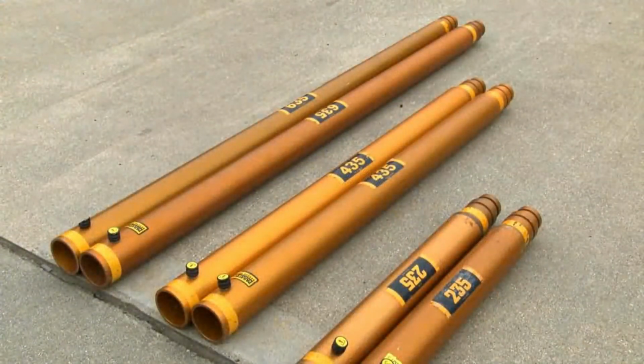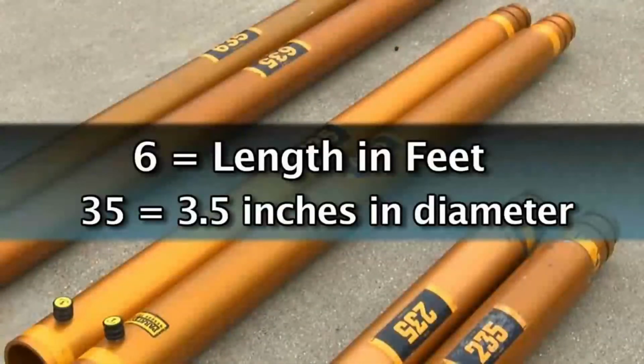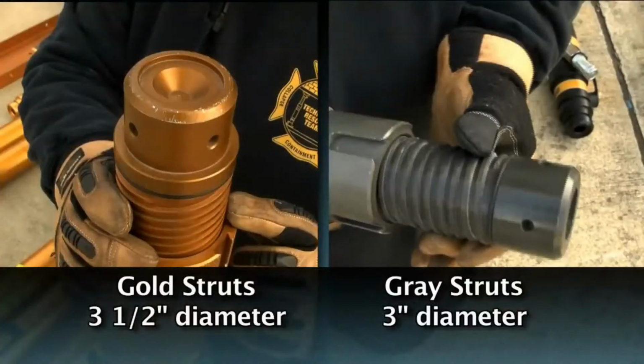Here we have 6 extensions: 2 235s, which are 24-inch or 2-foot extensions, 2 435s, which are 4-foot extensions, and 2 635s. The first number indicates the length in feet of the extension, and the 35 stands for 3.5 inches in diameter. The gold struts are 3.5 inches in diameter, and gray struts are 3 inches in diameter.